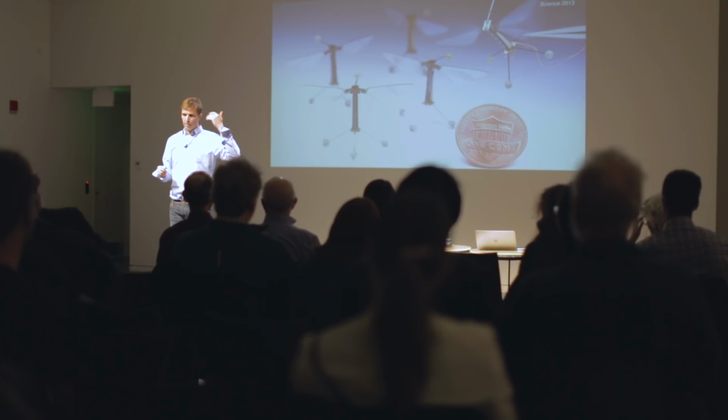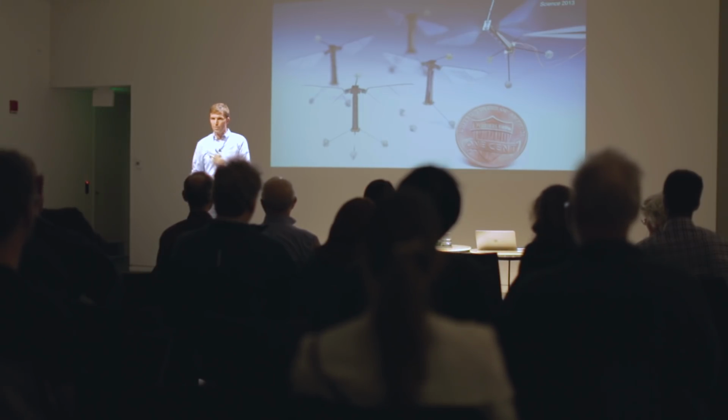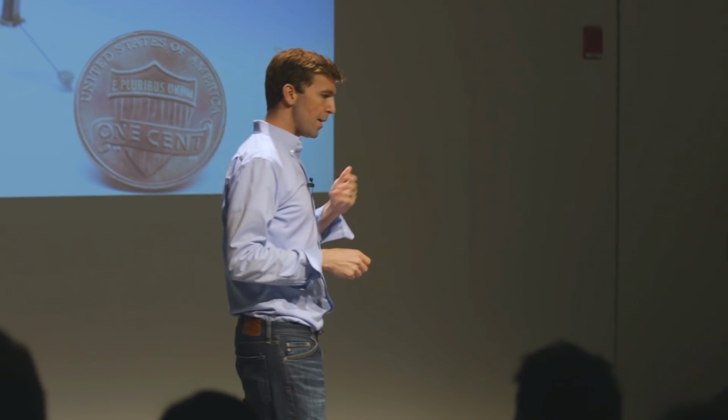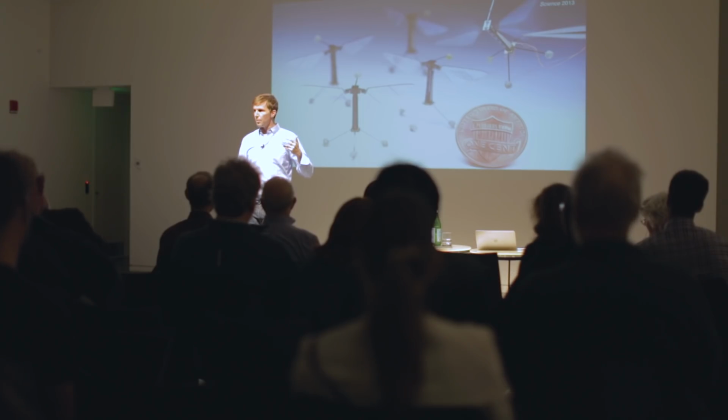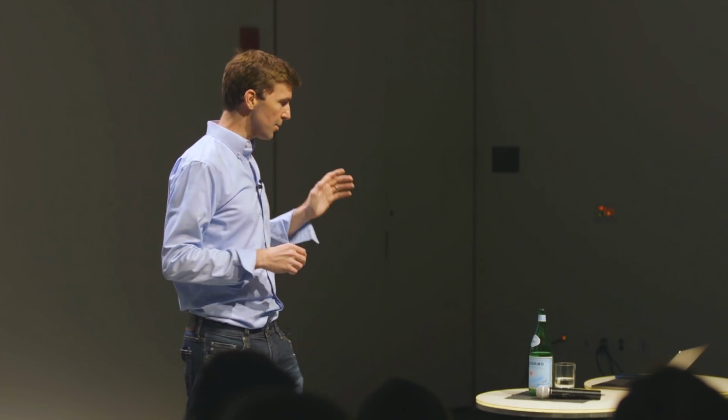I'm an ignorant roboticist, so I just said, okay, that means 2 degrees of freedom, 2 actuators per wing. But it turns out that's not a very efficient way to do this, because as you're actuating these devices, and we happen to actuate them at resonance for purposes of efficiency, you have a 2-input, 2-output system that you're operating at one of the resonant modes, and you're going to be throwing away energy into the other resonant mode if you do that.